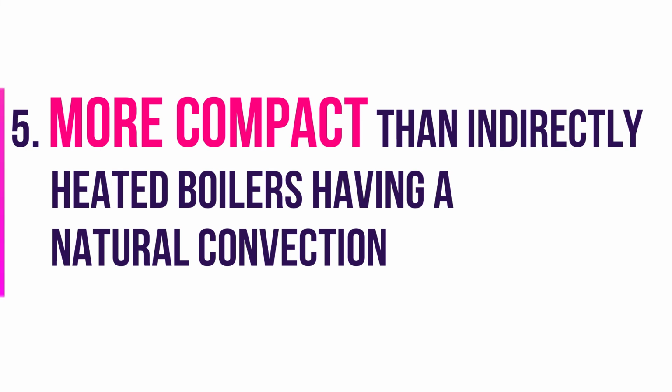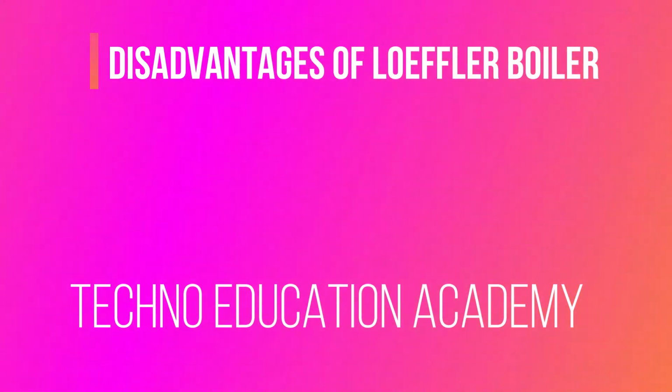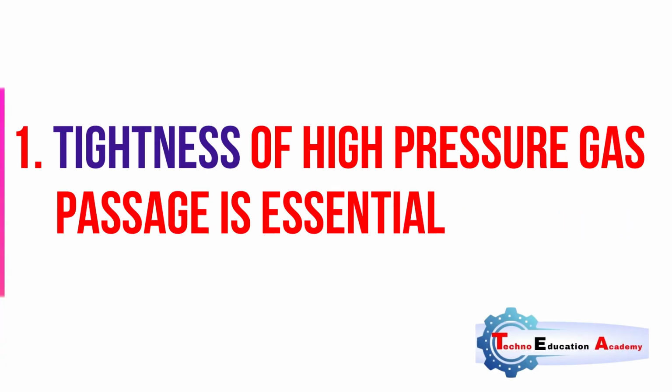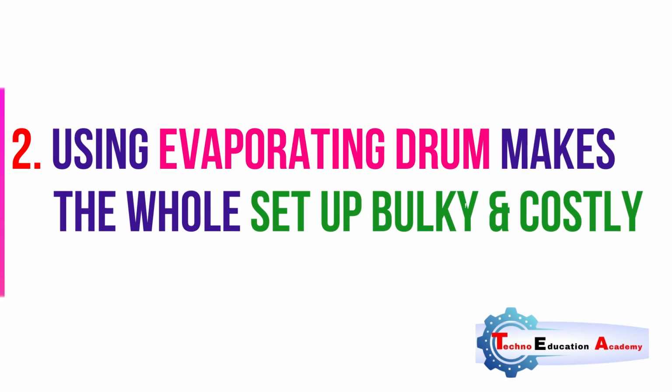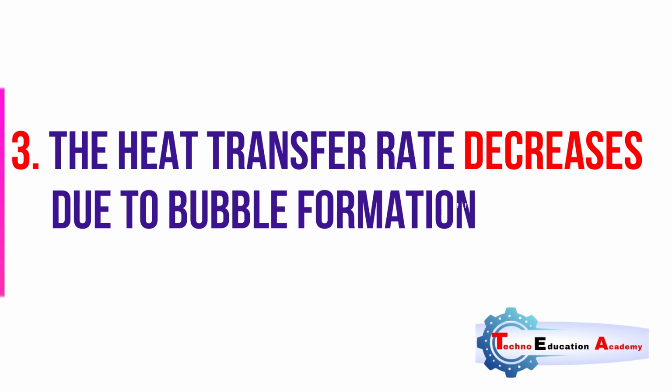Now what are the disadvantages of the Loeffler boiler? The first disadvantage: tightness of the high pressure gas passage is essential. The second: using an evaporating drum makes the whole setup bulky and costly. And the heat transfer rate decreases due to bubble formation.